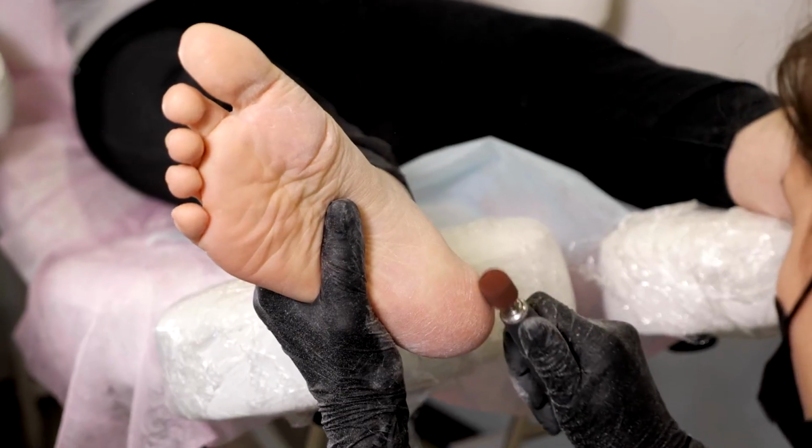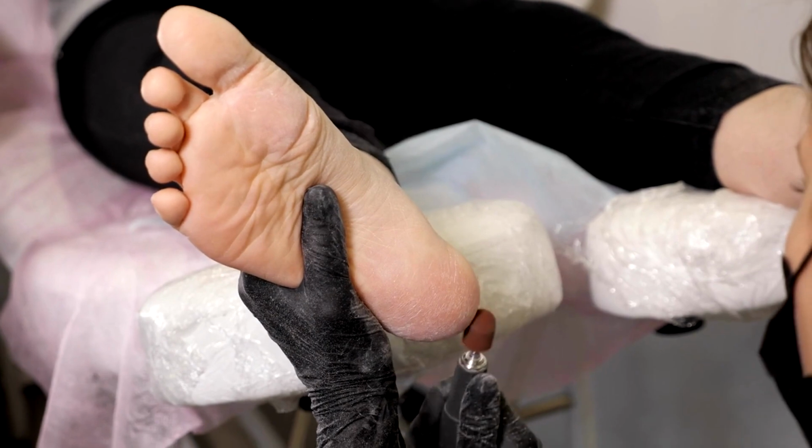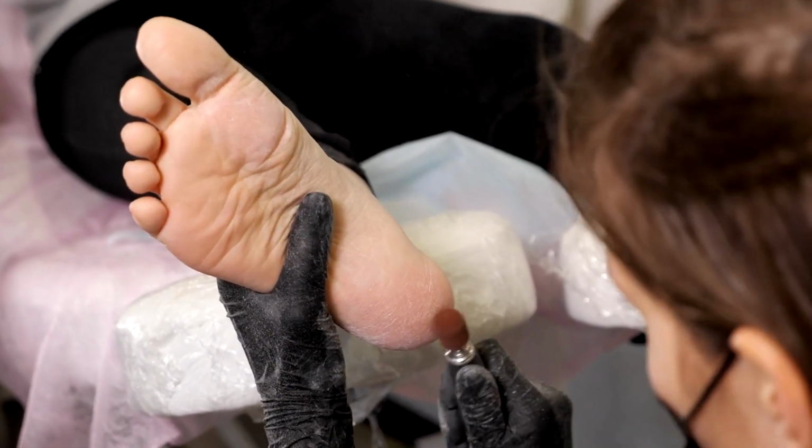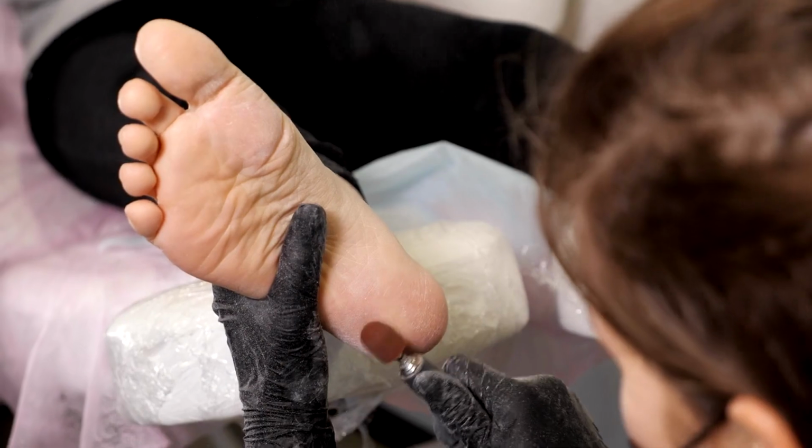Heeling error may be identified and corrected by a compass adjuster using a heeling error instrument. It is corrected by the appropriate placement of vertical corrector magnets below the compass.